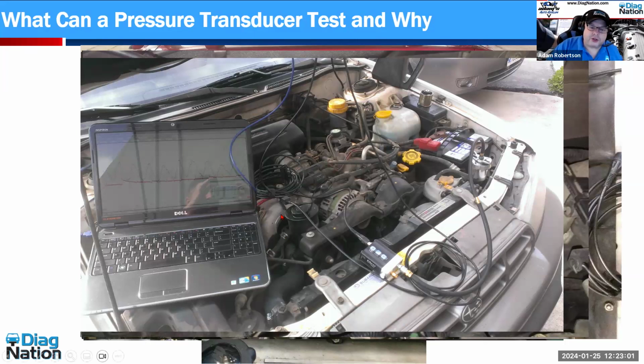Utilizing my pressure transducer, as you see here, absolute in this case, hooked right into my radiator pressure testing cap. So I just pulled the little bulb off of it, plugged it in. Now I'm reading hydraulic pressure in the cooling system. Now think about this one.